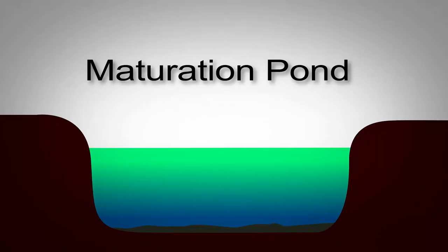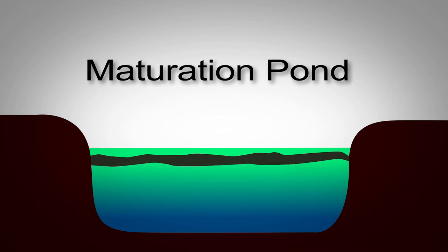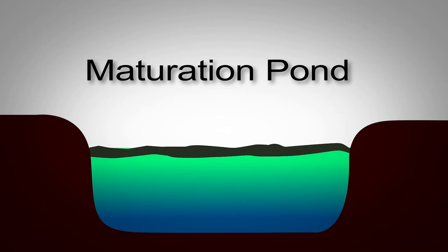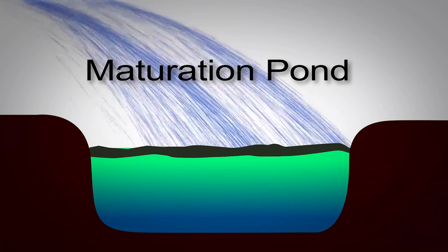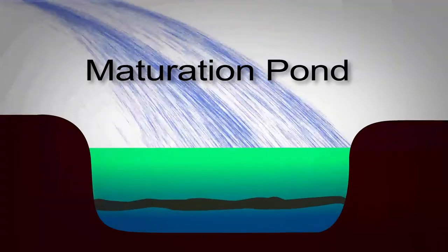Sometimes maturation ponds suffer an inversion event at the change of season, where the bottom sludge suddenly rises, often overnight, and covers the pond. This is a natural event, and generally the best means of repairing the damage is to use a travelling irrigator spray to sink the floating sludge. Seek expert help if required.